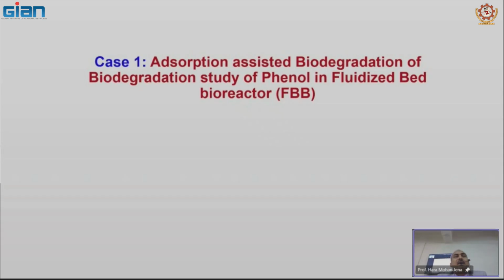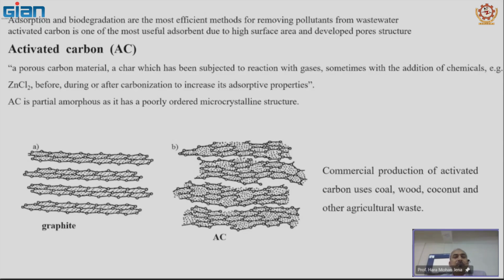Now I am taking two very specific case studies on the fluidized bed bioreactor. One is the adsorption assisted biodegradation study of phenol in a fluidized bed bioreactor. As we know, adsorption and biodegradation are the most important methods for removing pollutants from wastewater, especially organic pollutants. The most commonly used adsorbent is activated carbon, because of its high surface area and very well developed pore structure.